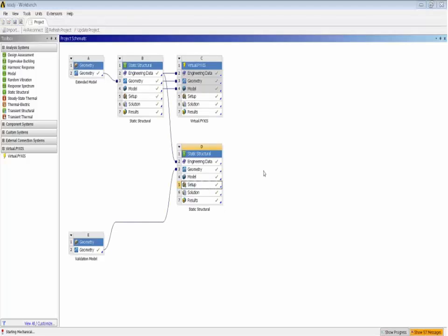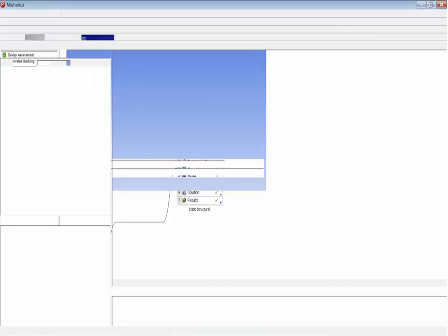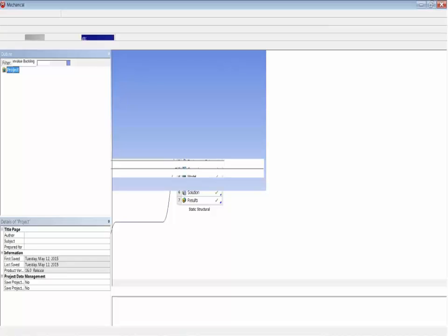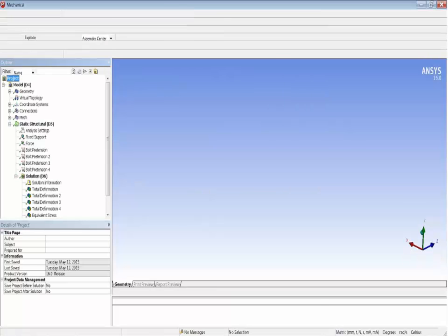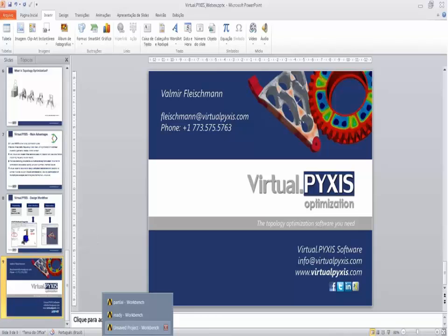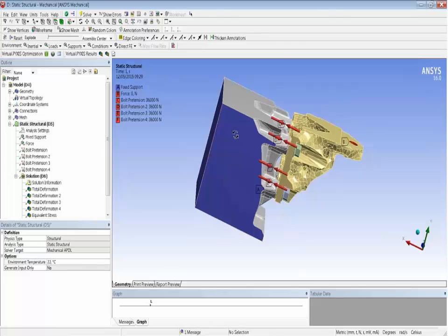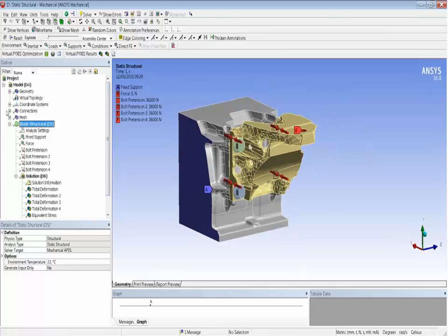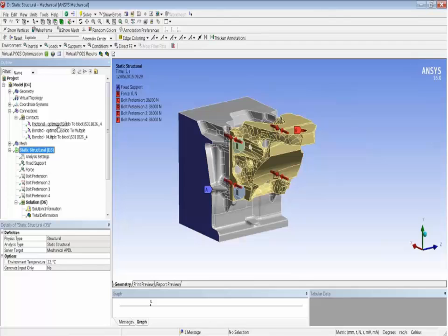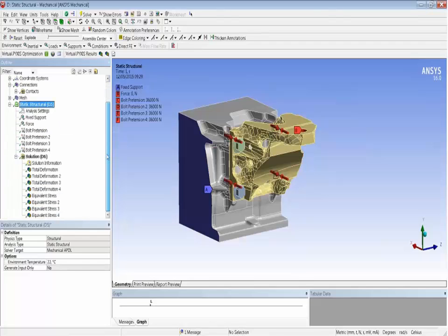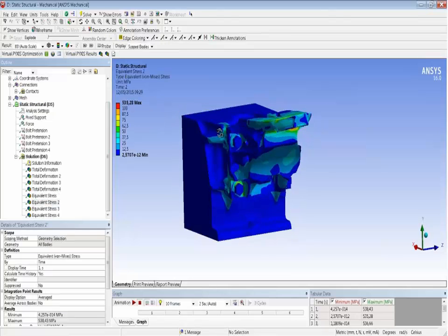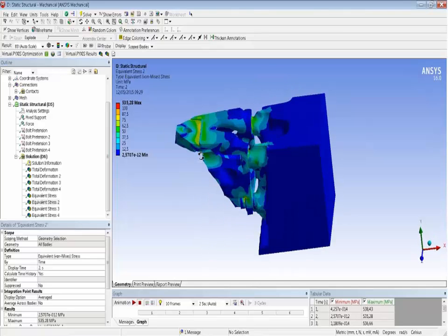I just open it to show you. So after that, when you have the assembly model in SpaceClaim, you can just replace the initial extended design, which was as I showed you before. And now, for example, you can replace it with this new condition. And very easily you can just refresh your contact region. This was already done. And after that you can have the solution of your model. And here you can compare the stress and displacement as you want, for example.